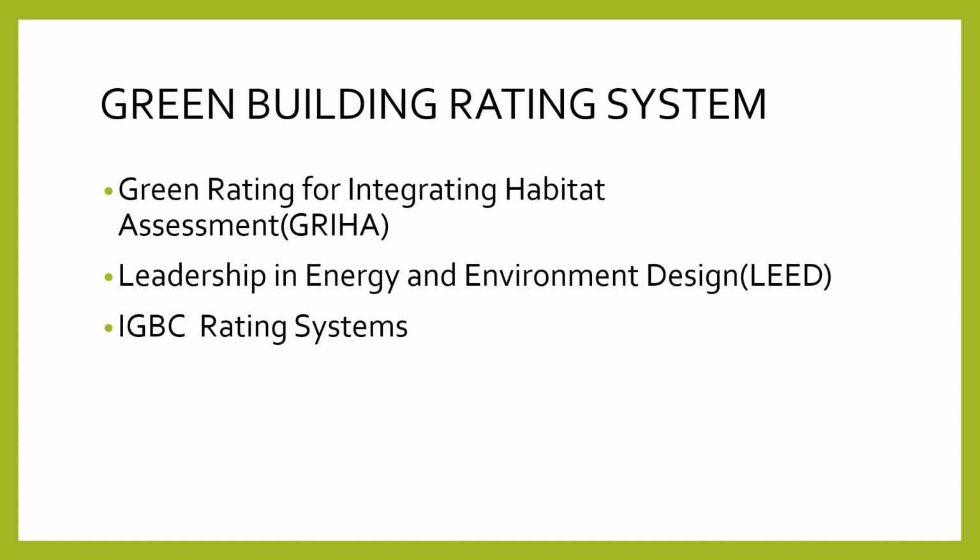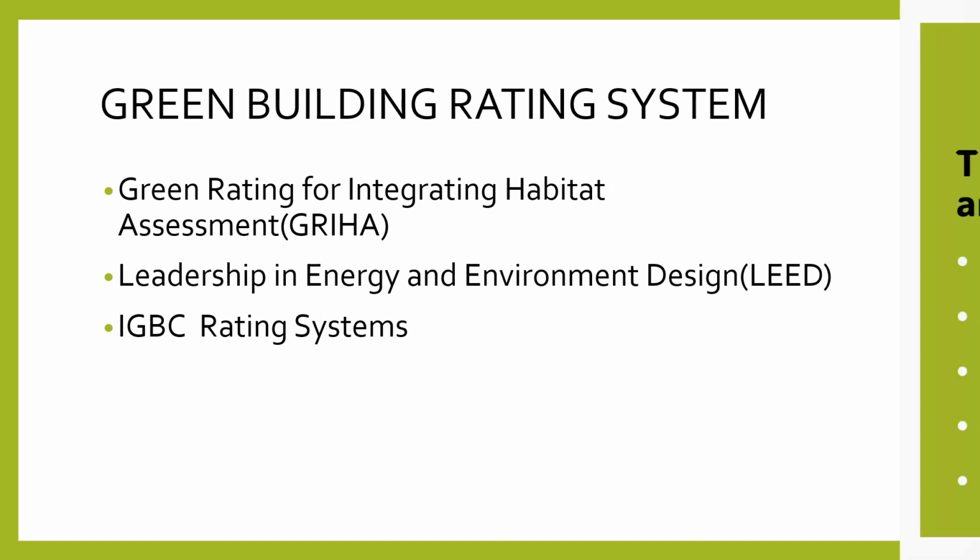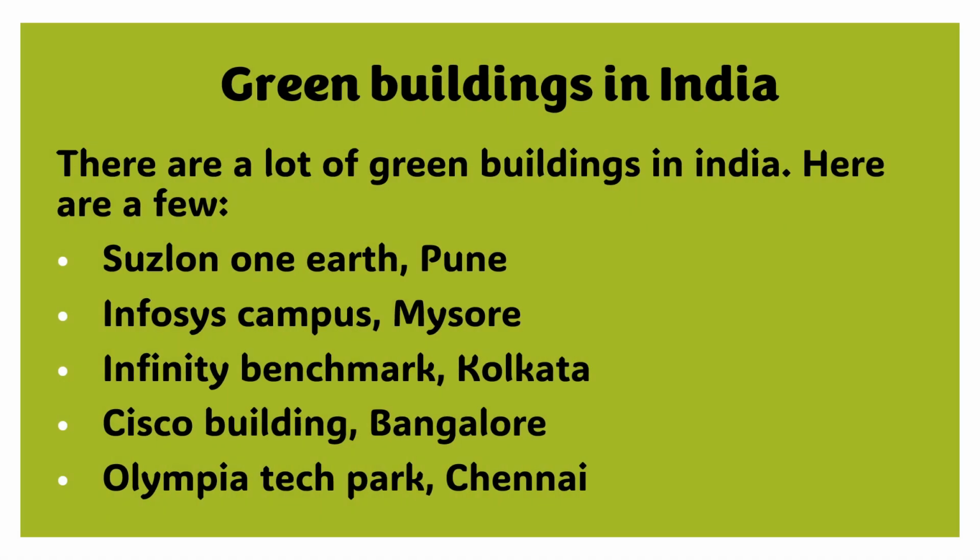The steps for the LEED procedure are: online project registration, submission of documents to IGBC, third party assessment, final documentation, site visit by IGBC, final review and award of rating, acceptance of rating, and finally IGBC issues the certificate. And now we're going to discuss a few of the green buildings in India.